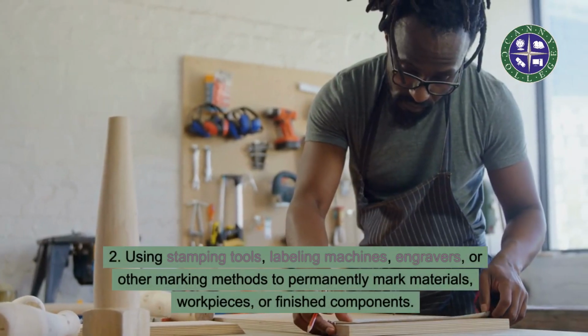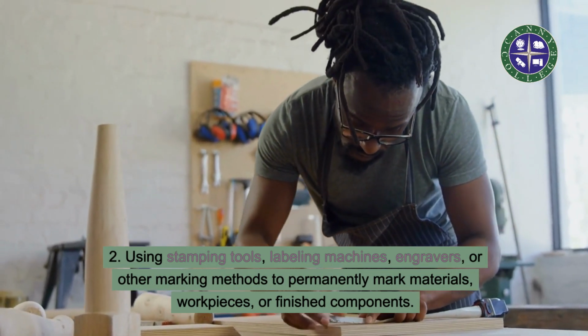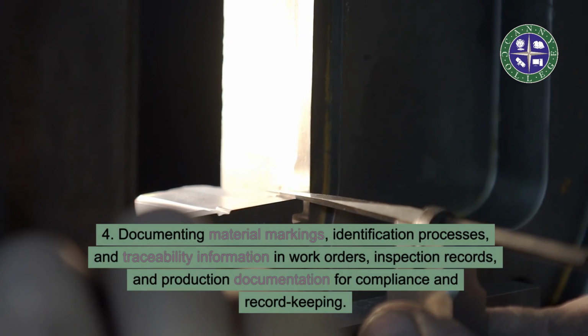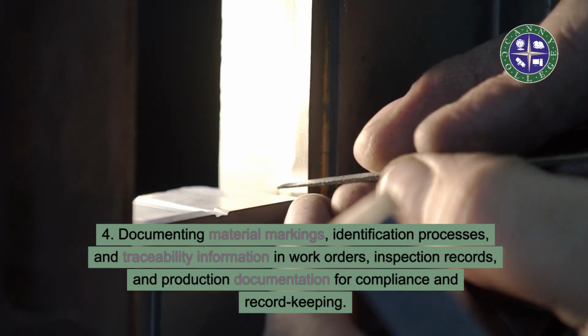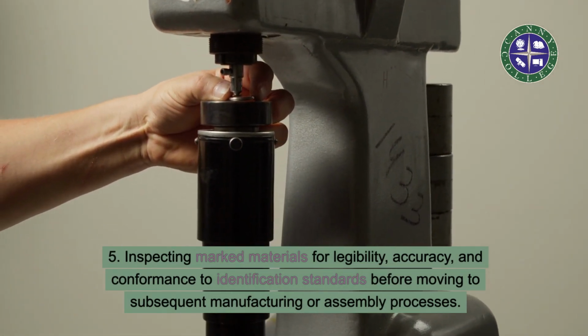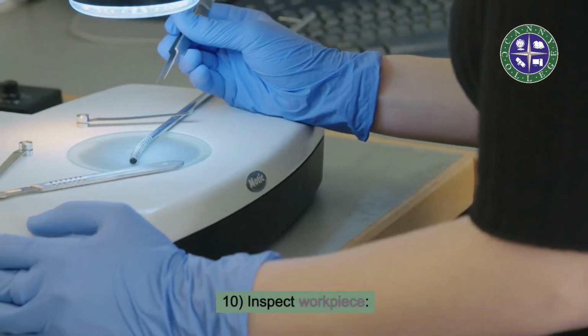2. Using stamping tools, labeling machines, engravers, or other marking methods to permanently mark materials, workpieces, or finished components. 3. Following material identification standards, color coding systems, or labeling requirements specified by project specifications, customer requirements, or industry standards. 4. Documenting material markings, identification processes, and traceability information in work orders, inspection records, and production documentation for compliance and record keeping. 5. Inspecting marked materials for legibility, accuracy, and conformance to identification standards before moving to subsequent manufacturing or assembly processes. 10. Inspect workpiece.